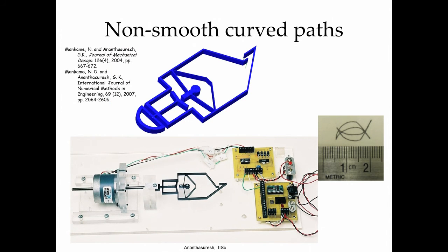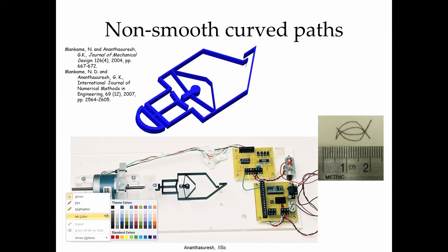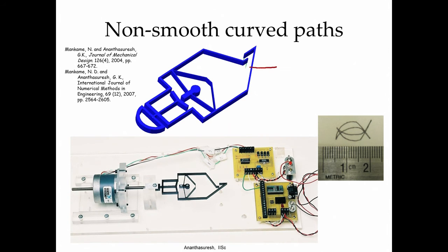Here is one for tissue cutting. There are 2 needles here, one over there, and another one whose tip you do not see, in this position. It is a planar mechanism, basically needles are over there. Okay. And you have one actuator here that goes back and forth. It is a stepper here, it can be any actuator. When this goes back and forth, these tips here will trace a complex path like this, and this one goes like that. There are 2 paths, let me change the color for the second one.